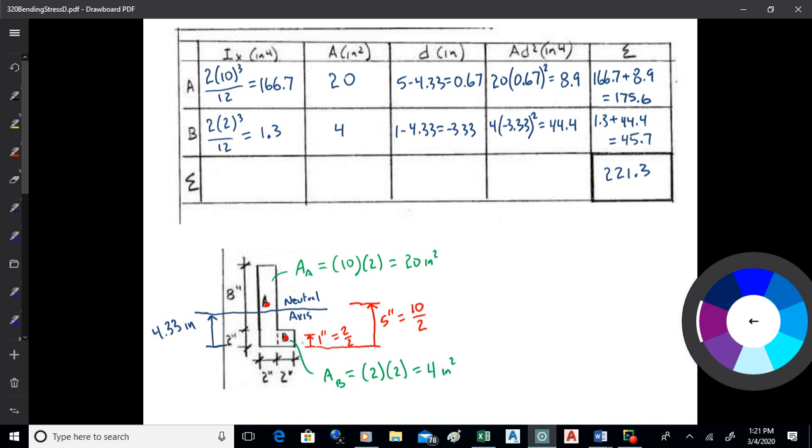All right with that? Okay. So that's how that goes. Now, I'll point this out again, but that's a negative number, but it doesn't matter because it goes inside the parentheses, you square it, so those negatives always go away. So even if something is below the axis, it still will get you a positive moment of inertia. The only time you get a negative moment of inertia is if you're doing cutouts out of a shape, then it'd be negative. But other than that, the terms are not negative, regardless of where they're positioned.